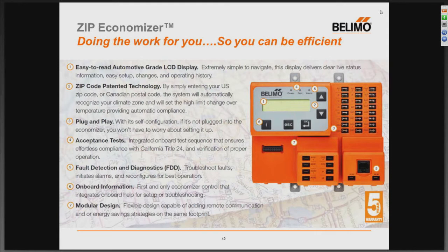The acceptance test, the verification of operation. It's that integrated onboard test sequence that just makes sure you're fully compliant with California Title 24 in this case, but also make sure that you are rest assured that everything's working before you leave. Fault detection and diagnostics. We'll troubleshoot faults, we'll initiate alarms, and we'll reconfigure for best operation.